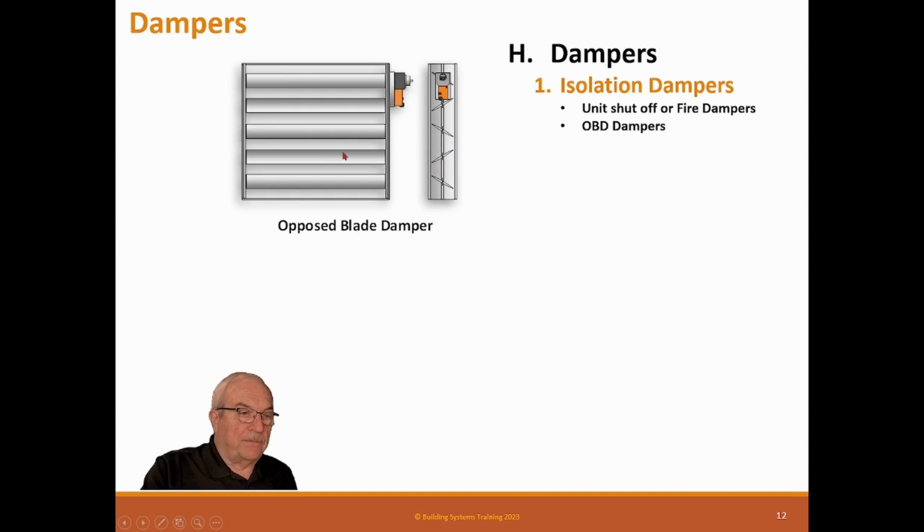Now, all the dampers we have in air systems, we have what's called low leak dampers, we have ultra low leak dampers, and we have standard dampers. Standard dampers leak quite a bit. I mean, they're leaking somewhere around 3 to 5% of air. A low leak still leaks 1.5% or so. Ultra low leak maybe 1% or below, but they're never seal tight.